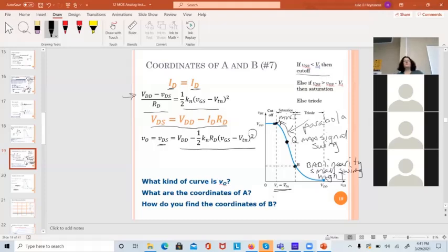And you see, there's all kinds of tricks people use to get the current to a minimum. One of the things they use is something called pulse width modulation that you'll see a lot. The Arduinos use it for their analog output, but it's used a lot in power circuits to minimize the amount of power you're losing, which is a big deal for power people.